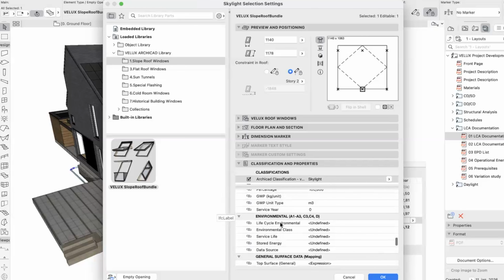So this is the whole secret about Design LCA being an LCA-based design tool. When I need to design with a lower carbon footprint, I'll find the layer that has the biggest CO2 impact. It was the foundation layer. And I can see within the foundation, my biggest problem is the concrete.